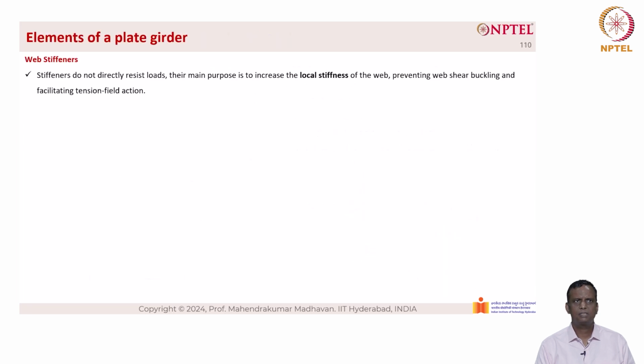Now the web stiffeners do not directly resist loads. Their main purpose is to increase the local stiffness of the web, preventing web shear buckling and facilitating tension field action as I described previously.